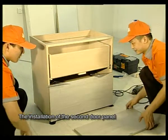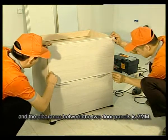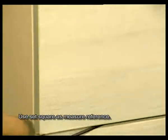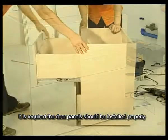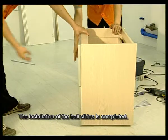The installation of the second door panel is the same as the first door panel, and the clearance between the two door panels is 2 mm. Use a set square as measure reference. It is required that the door panels be installed properly and the clearance be even. The installation of the ball slides is completed.